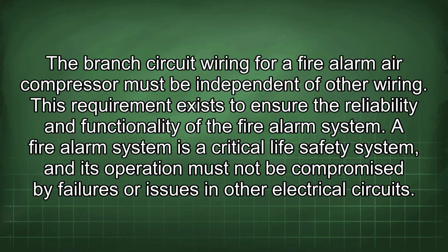The branch circuit wiring for a fire alarm air compressor must be independent of other wiring. This requirement exists to ensure the reliability and functionality of the fire alarm system. A fire alarm system is a critical life safety system, and its operation must not be compromised by failures or issues in other electrical circuits.